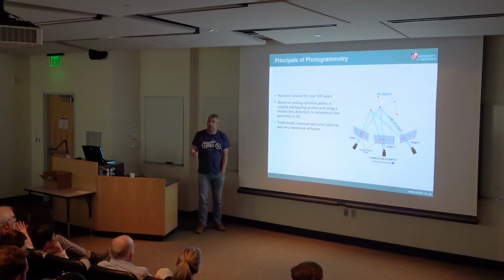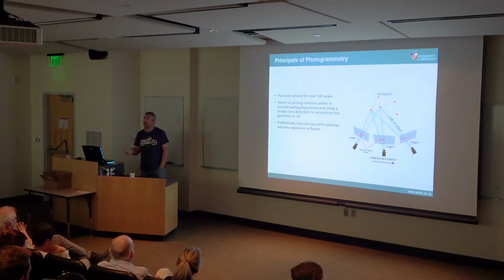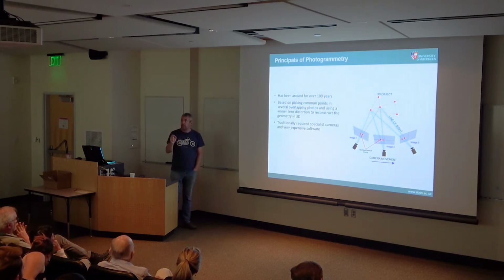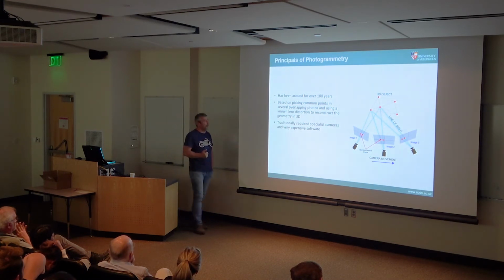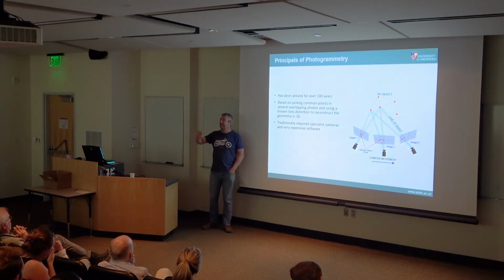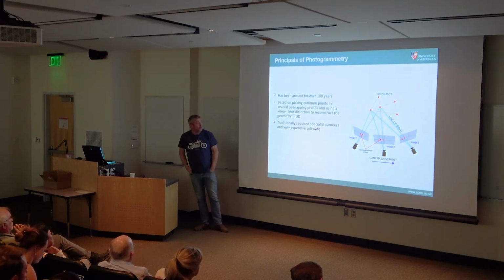But what's new is that in around 2010, a whole bunch of new algorithms for doing this became publicly available. Previously, the photogrammetric, or the geomatics community had been obsessed with detail and getting everything super precise. And then this thing called structure from motion came along, and it basically said, we don't have to be millimeter precise. We're trying to reconstruct it. And it also does it in quite a clever way. It builds a rough model first of all, and then uses that to position the camera positions and solves it then so you can build the fine model.